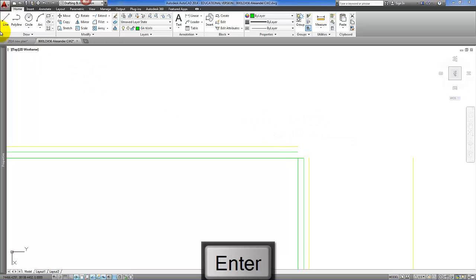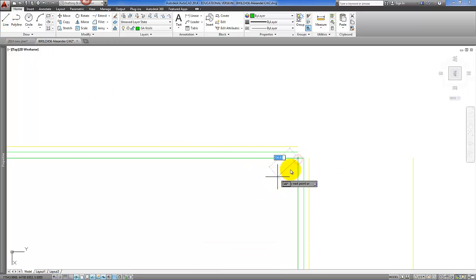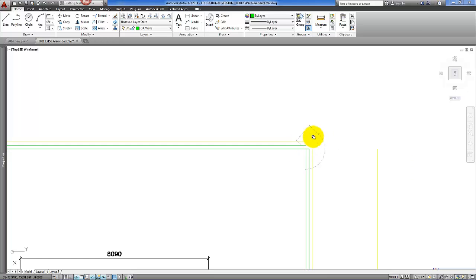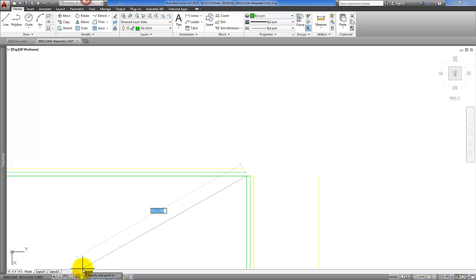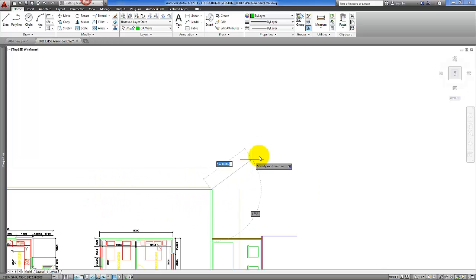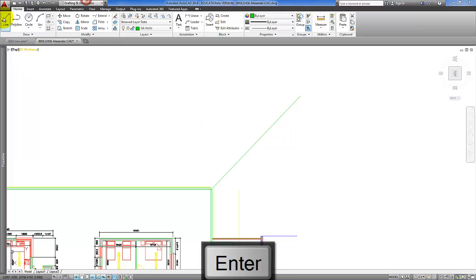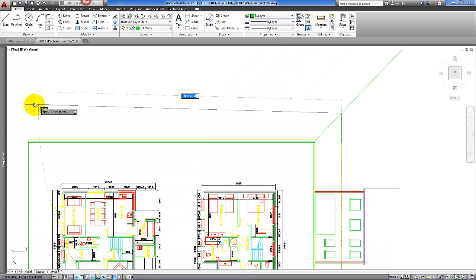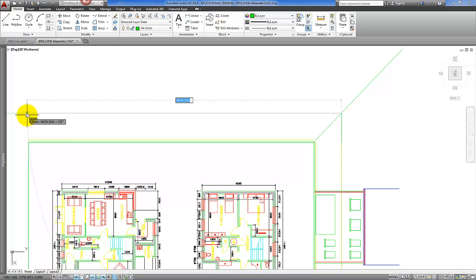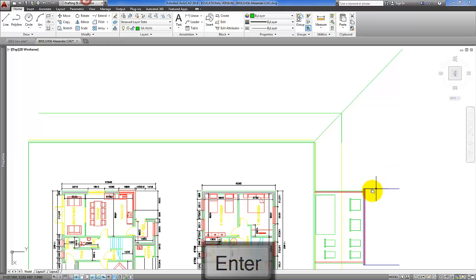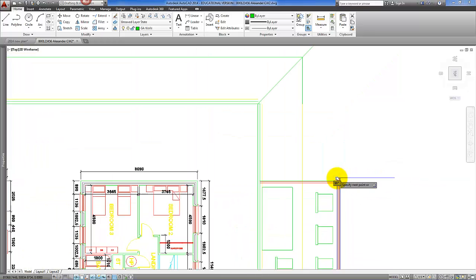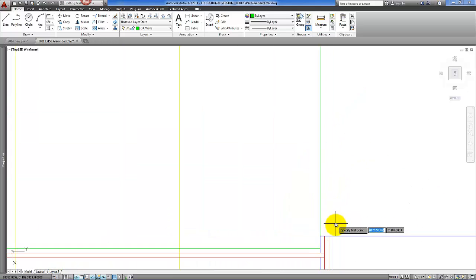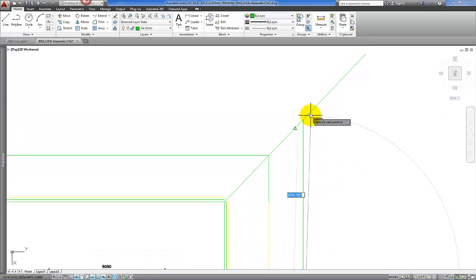Now there will be other lines there that we might be able to transfer through, so if we draw a line from that intersection or the corner of the first rectangle, and making sure that the ortho is on and also has the 45-degree angle set, we can draw a line up at 35 degrees, and from that then we can take a line that will show us exactly where the first floor level will be, and similarly with the underside of the fascia we can do the same, and also the top of the fascia.